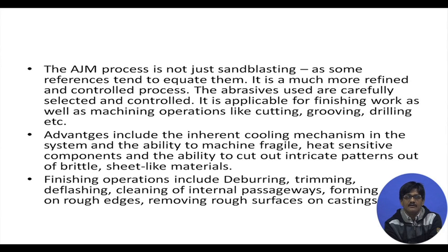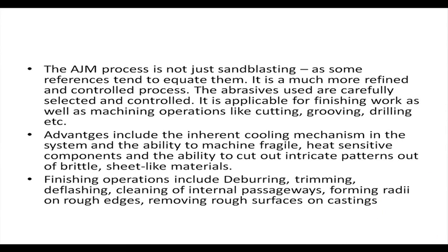AGM is much more refined and a much more controlled process. The abrasives which are used are carefully selected and controlled, and it is applicable to finishing work as well as machining operations like cutting, grooving, drilling, etc. With sandblasting, we cannot do cutting, grooving, etc.